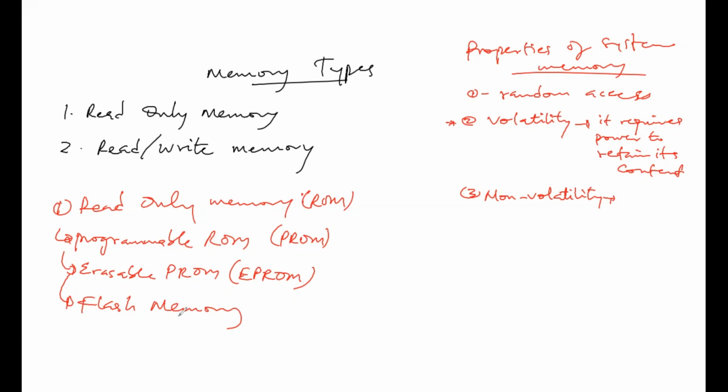Now, let me talk about the electrically erasable PROM first, which is the EEPROM, right? It allows for further flexibility by allowing the user to selectively erase content. So there's no need for a special ultraviolet chamber to erase the entire content. That's just the difference between the EEPROM and the EPROM.